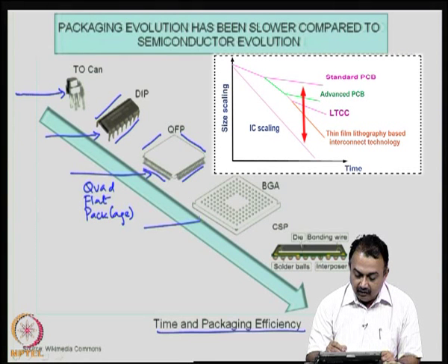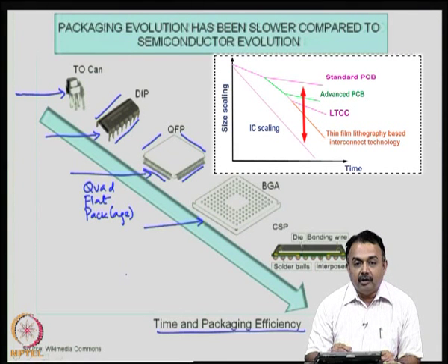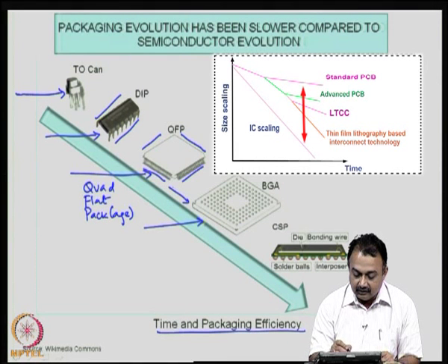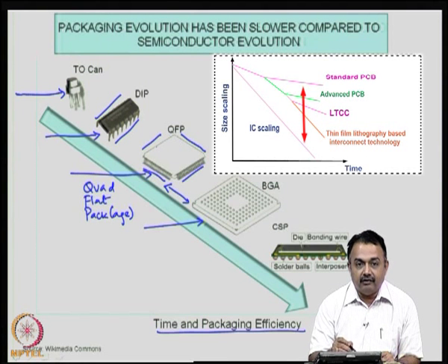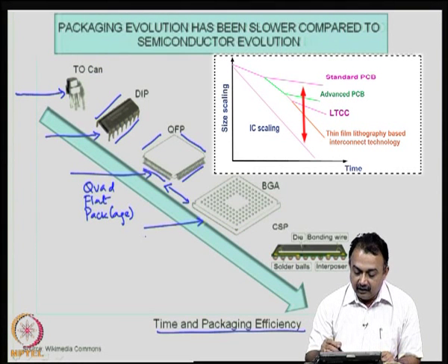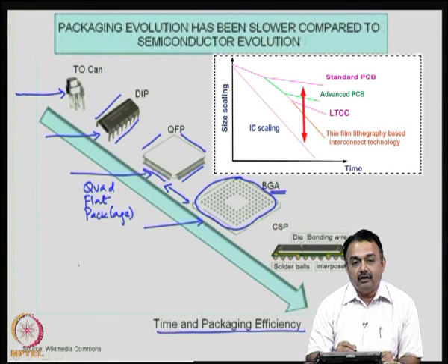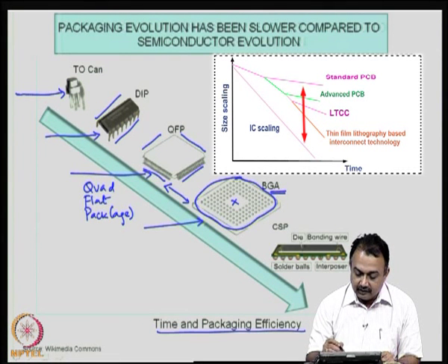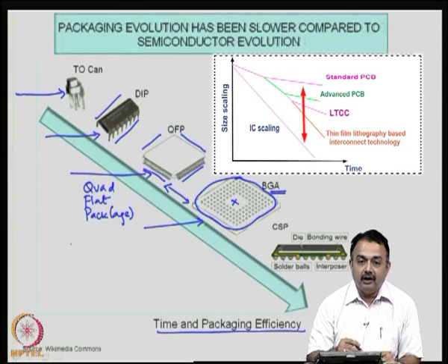Now, today we are into the world of ball grid arrays. As you can see, the difference between these 2 packages, the bonding here is at the periphery in the QFPs, whereas in the ball grid arrays you can see the input output pins occupy almost the entire area of the die, except at the center, which is probably used for heat dissipation.